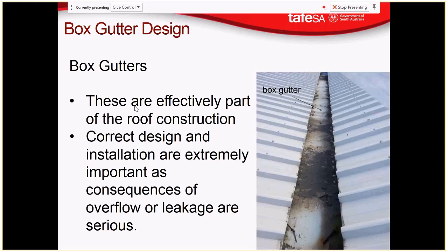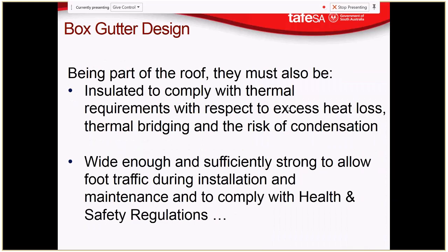So these are effectively part of roof construction. Correct design and installation are extremely important, as the consequences of overflow or leakage are serious, because typically you're dealing with an internal space underneath the box gutter. Being part of the roof, they must also be insulated to comply with thermal requirements with respect to excess heat loss, thermal bridging, and the risk of condensation. So for all your roofing insulation, you have to carry that insulation underneath the box gutter as well.